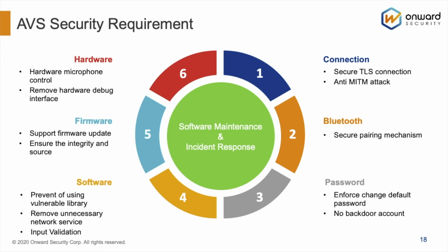And for the firmware, each device has to support a firmware update mechanism. Besides, you also need to ensure that during the firmware update, the device has the capability to verify that the integrity and source of the firmware update are trusted. It cannot be attacked by someone.